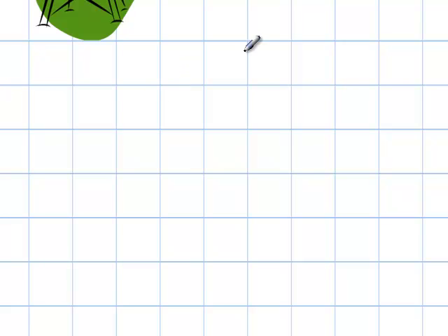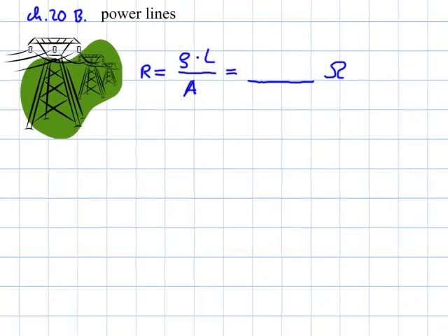So that's just a matter of plugging in numbers. Use the equation that connects resistance with resistivity. The area is given in square meters in the problem. The length is 10 kilometers, respectively 10,000 meters. And the resistivity, you look up in the chapter, it lists it for aluminum as 2.82 times 10 to the negative 8 ohm meters. Units, the meters and meters squared will divide out, and you're just going to be left with ohms.